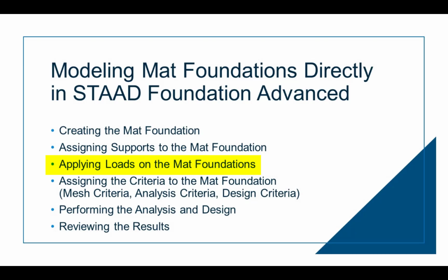Please note that we are creating these loads in STAAD Foundation Advanced since we created this mat directly in the program. Therefore, no loads were transferred into the program from a superstructure model. When a superstructure model is imported, the support reactions from the columns are brought into STAAD Foundation Advanced during the import process and will be converted into the loads automatically.